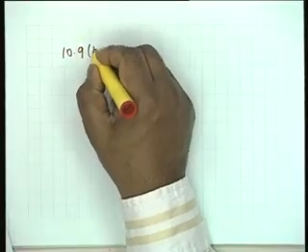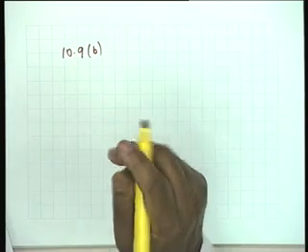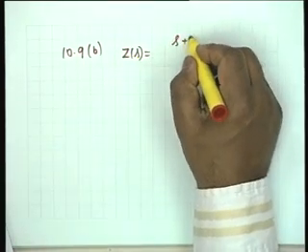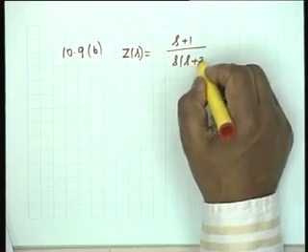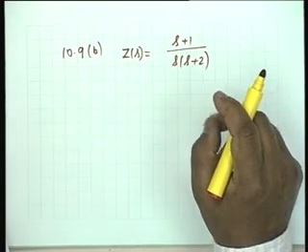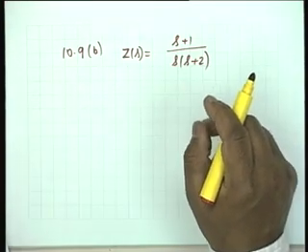And let's do 10.9 B. Just one more. It is given that this function is an impedance function, that is Z of s equal to (s plus 1) divided by s into (s plus 2). Synthesize the impedance by successive removal of j omega axis poles, or by removing the minimum real part on the j omega axis. You have to synthesize this by successive removal of poles on the j omega axis.